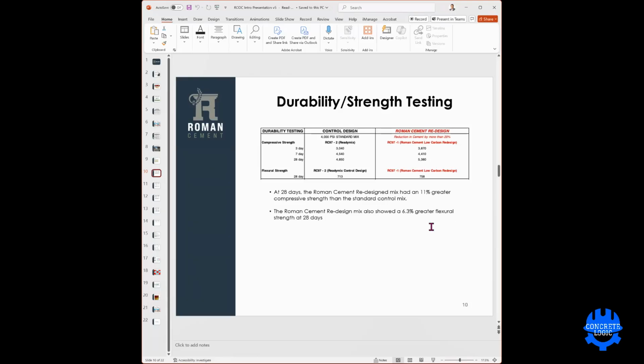But like I said, a compromise might be this blended SCM with pozzolan and limestone that would at least permit us to not have to use another silo. It would then fix the ratio of pozzolan and limestone, but that's not as big of a deal as the ratio of this blended material compared to the cement. That's the ratio that we want to have maximum flexibility to change at the batch plant.